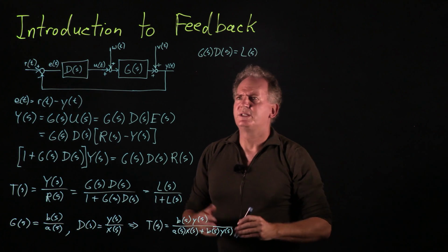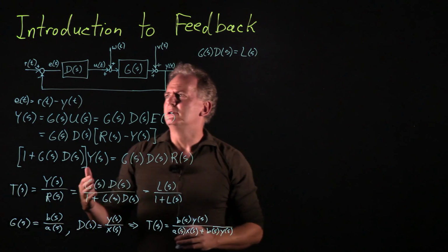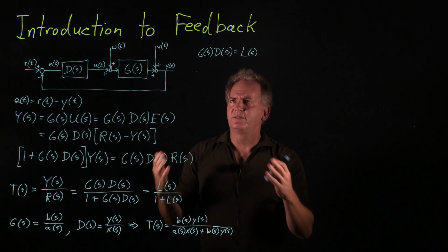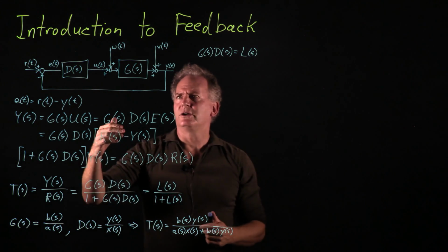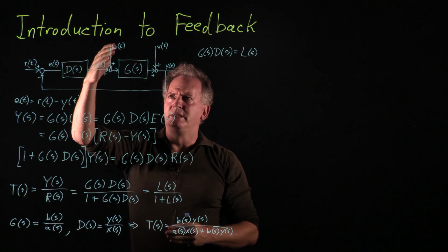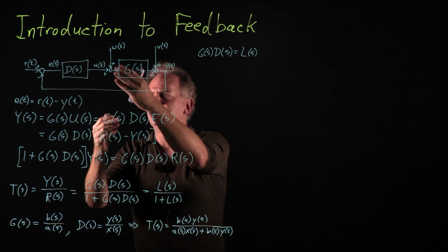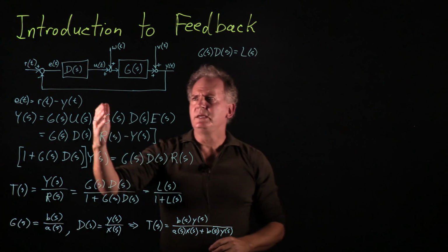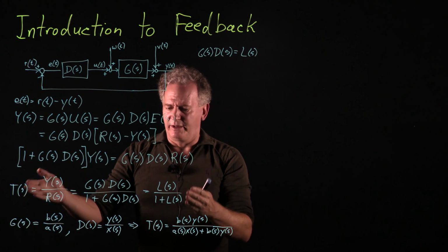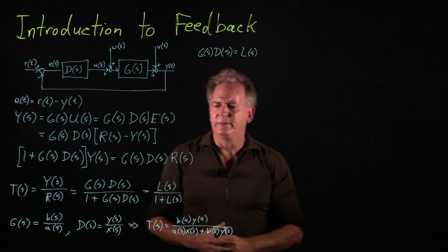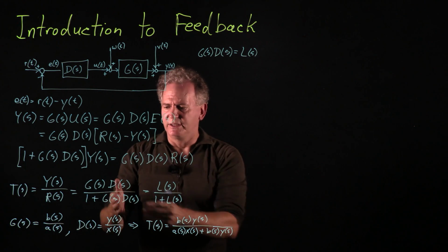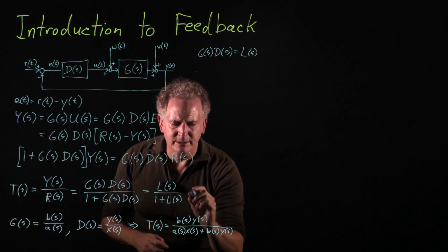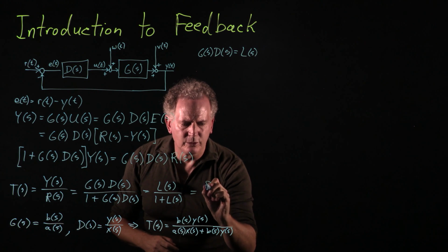And so then it's useful to consider not only the closed loop transfer function from the reference input to the output Y, but several other transfer functions that characterize relationships between, say, the disturbances and the output, or the disturbances and some intermediate variables like U and E, etc. The several relations that you get following a similar derivation like this can be written, and in all cases, including this one, the formula, if you want a mnemonic, is just the forward gain.